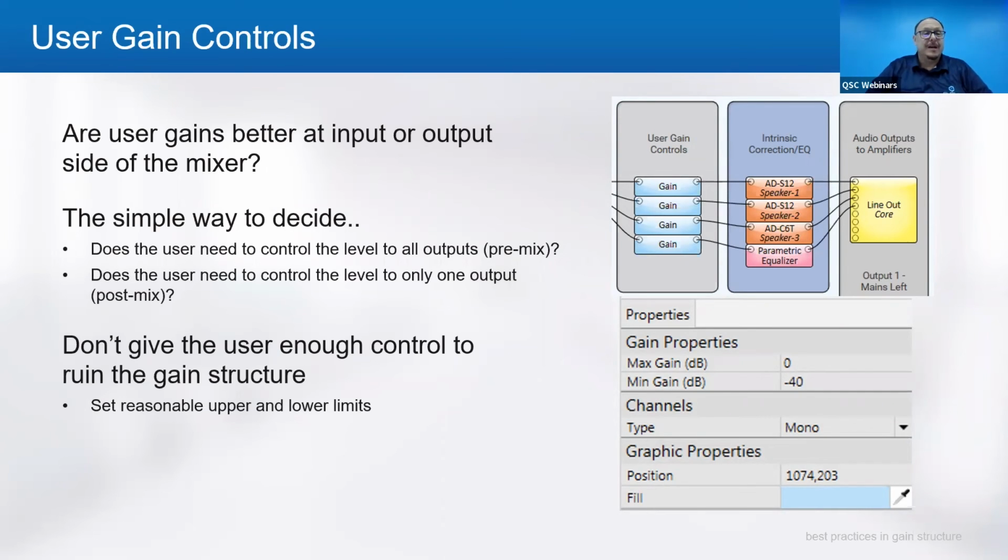User gain controls. Are user gain controls better at the input or the output side of the mixer? Well, the simple way to decide this is, does the user need to control the level of all outputs pre-mixer independently, or can you just simply give them one simple volume control to raise that volume up and down in the room?